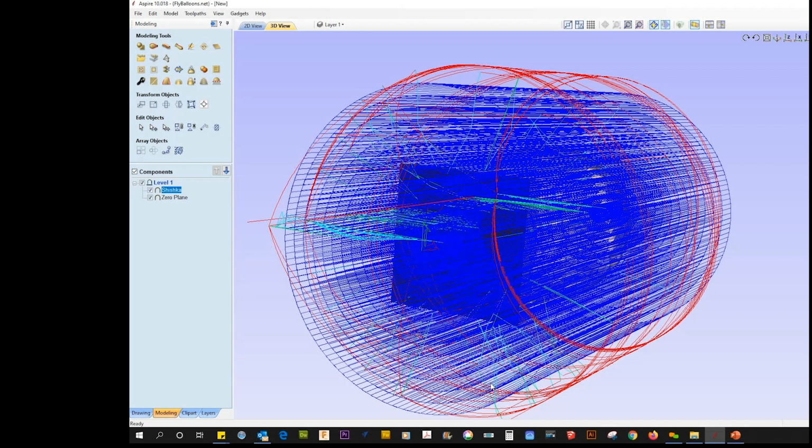But by cutting in the levels, you are allowing the machine to cut at a normal rate, which maybe even if you took off 3/8 at a time, it would still allow you to cut a little faster than trying to plunge at a deeper depth. So it's a safe way to do it, because if you normally try to run into the thickness of that material, you would definitely break a bit.